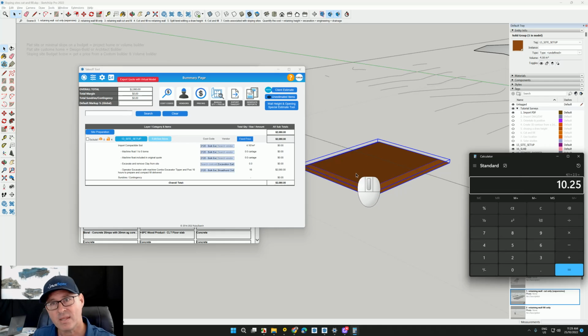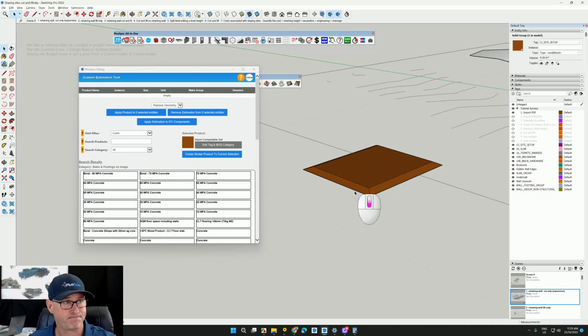Now one thing guys is it's so much cheaper to import fill than it is to export it, because most of the time you can get compactable fill for free delivered to the site. It just means that you probably need to level it, and if you're getting a lot of it, you can probably negotiate with the excavation company to actually level it for you. The more fill you put in, the deeper you have to put a pier through it to get to solid ground, so there are costs associated with that, and we'll talk about that a little bit more in the future.